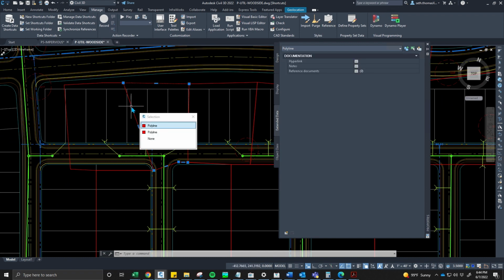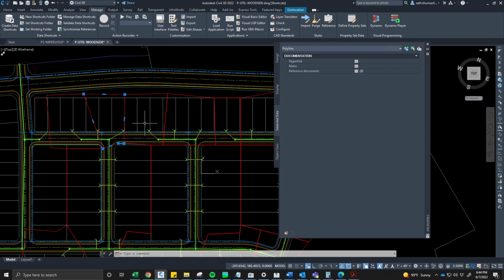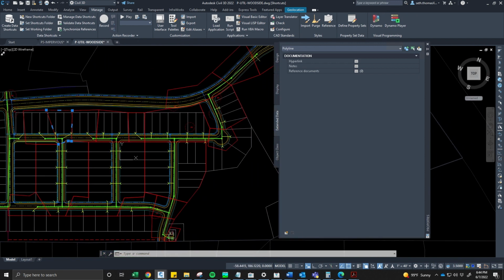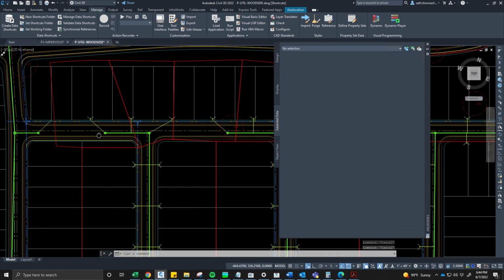The second part is your I&I areas. These are just the areas that are possibly going to be infiltrating the pipe, so we have to account for rainfall that could enter when we're sizing these pipes.